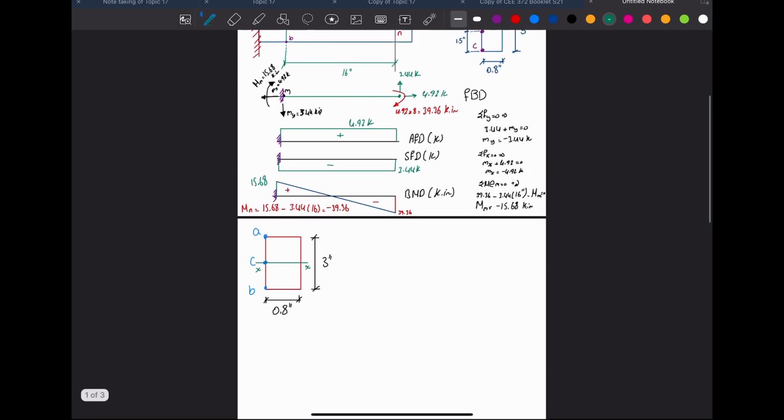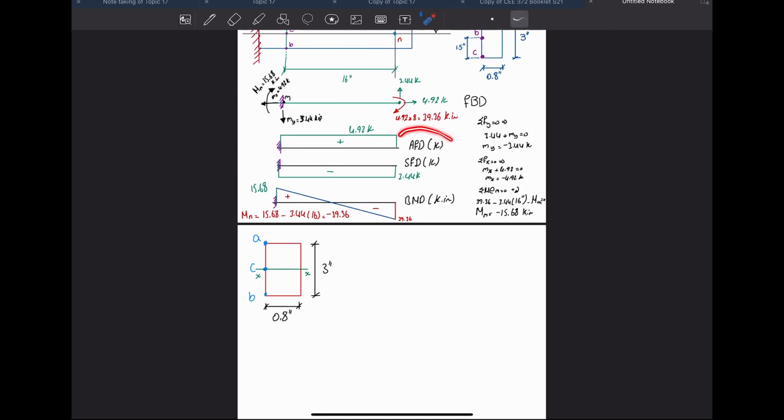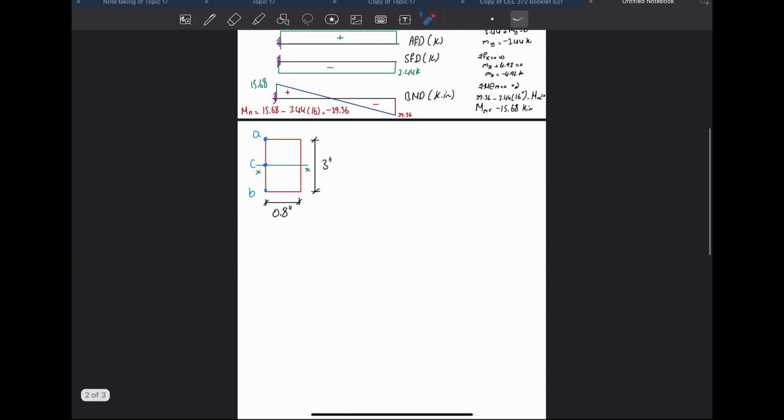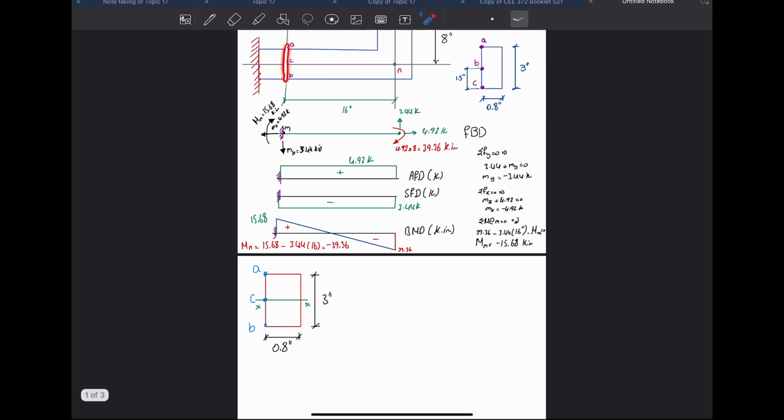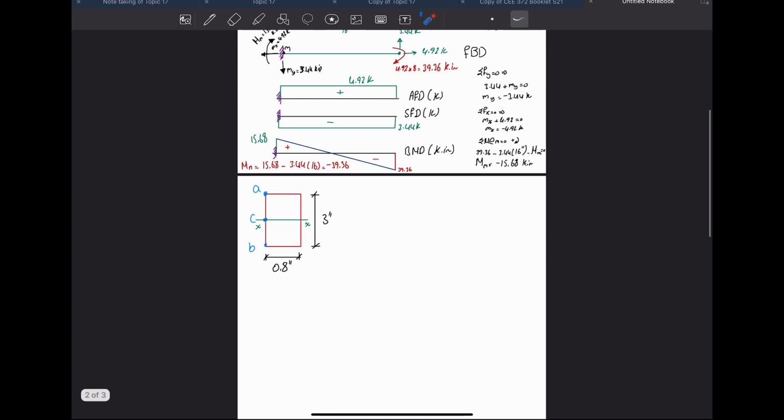After getting the axis of bending, let's now put the axial force, the shear force, and the bending moment on that cross section so that I can use these in the stress calculation. I want to study this section here. This section has internal forces here, here, and here. The section feels an axial force equal to 4.92, acting at the center. So I'm going to write N is equal to 4.92 kips. It's in tension, so it's positive.